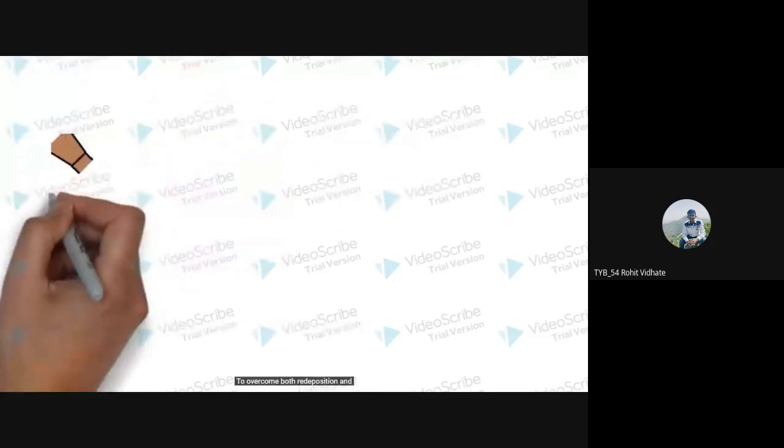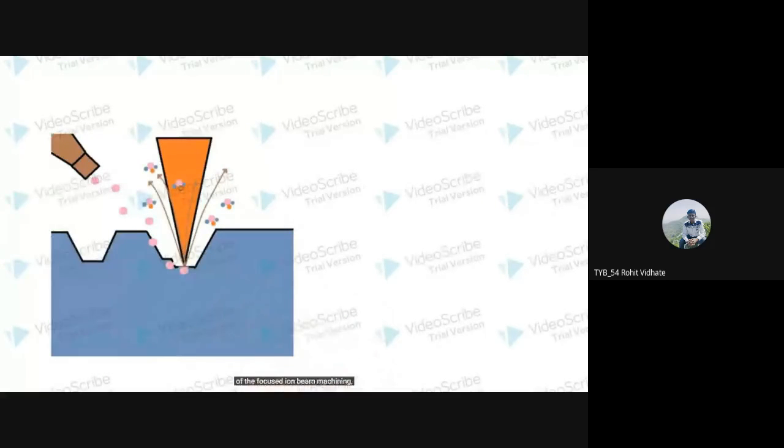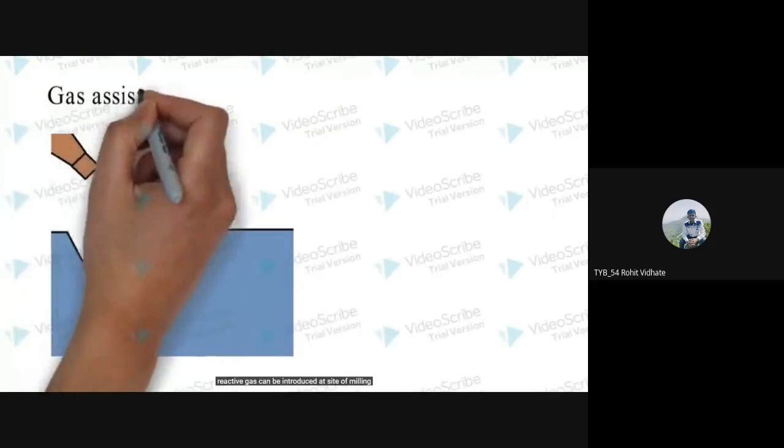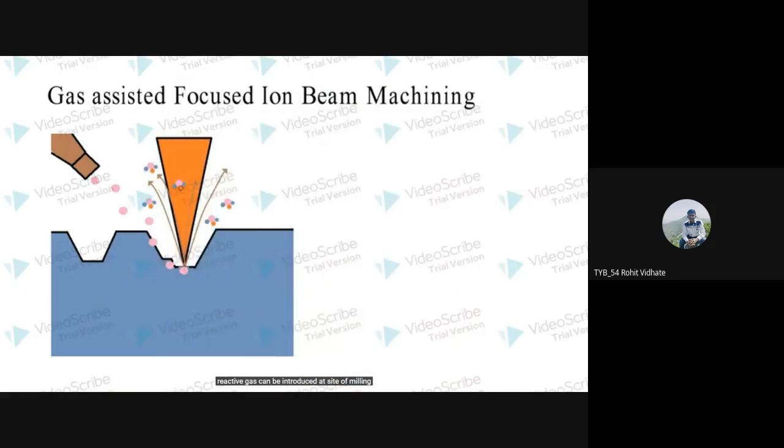To overcome both the redeposition and low material removal rate problems of focused ion beam machining, reactive gas can be introduced at the site of milling. This type of milling is called gas assisted focused ion beam machining. So this is GIS, that is gas injection system, in addition to the ion beam and workpiece. So this reactive gas is incident on the milling site.